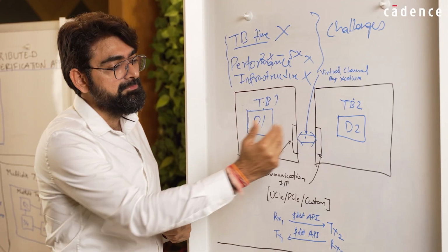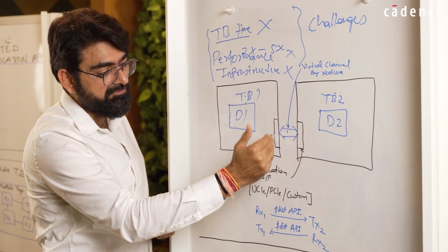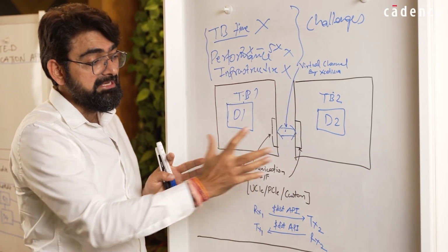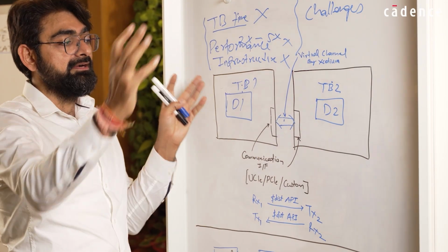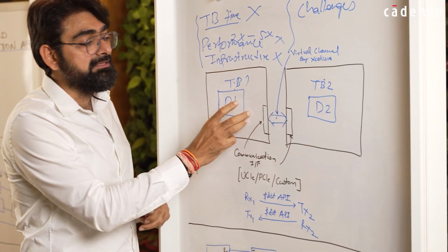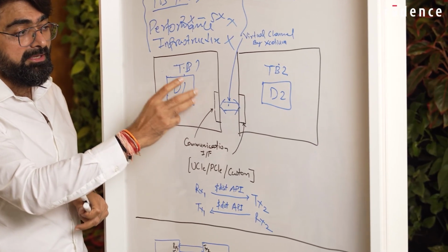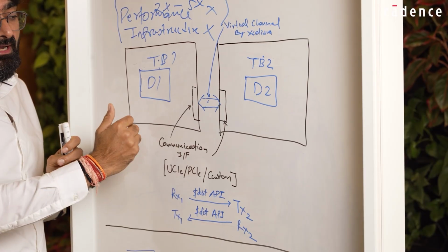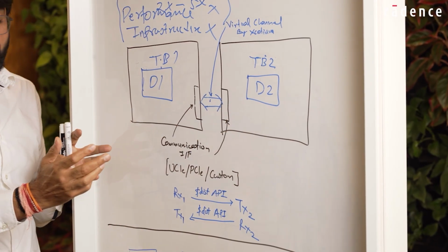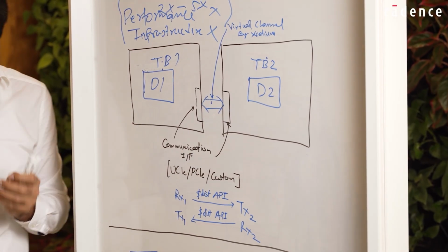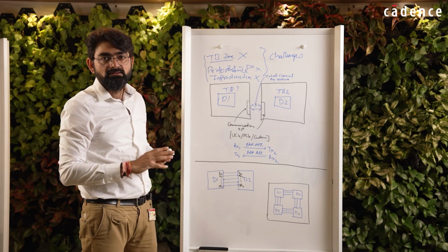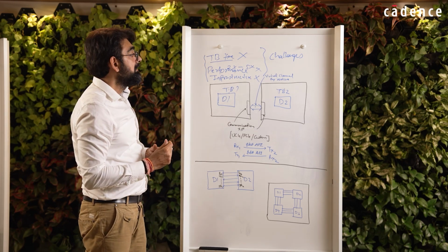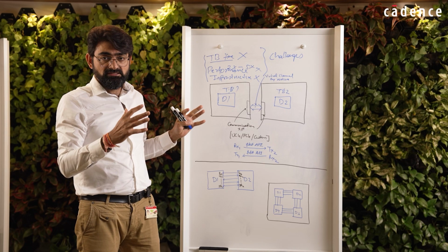However, with the distributed simulation app, you can just define these without really creating any Verilog or any top, without integrating these two together or having a test bench for these, reusing the existing monolithic one. You can actually do a really shift left by starting verifying the multi-die configuration along with single die itself. So it's a big shift left as well, naturally. So this is, in very simple terms.